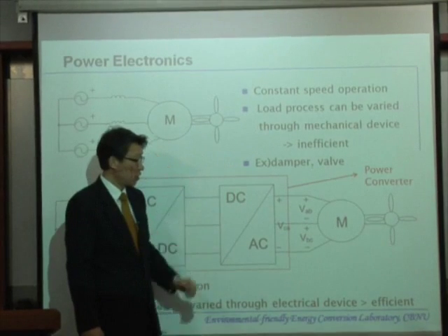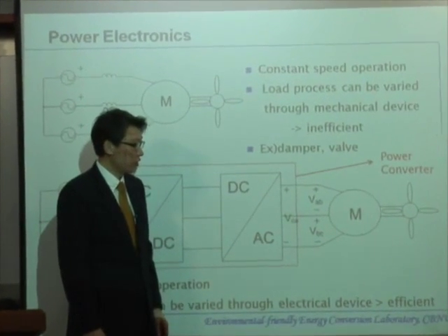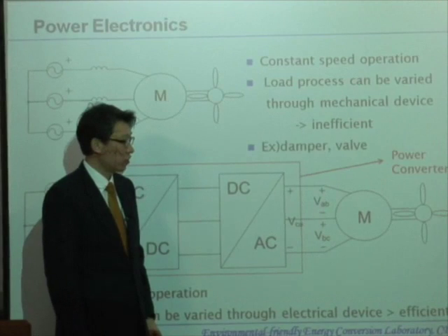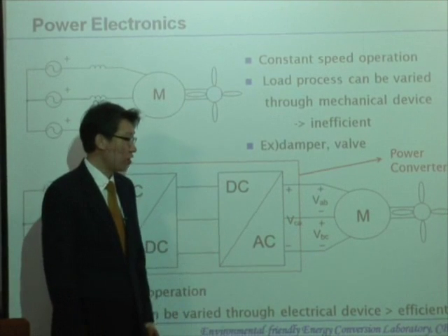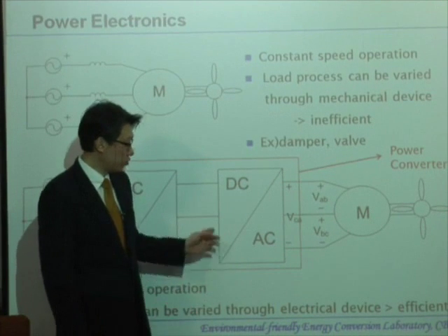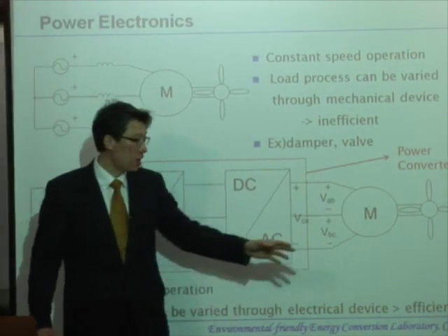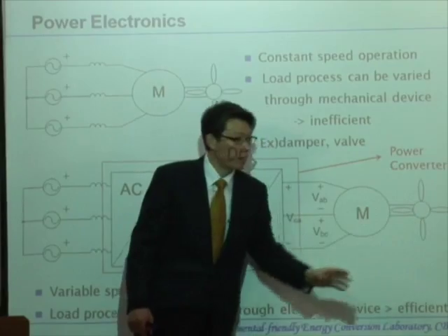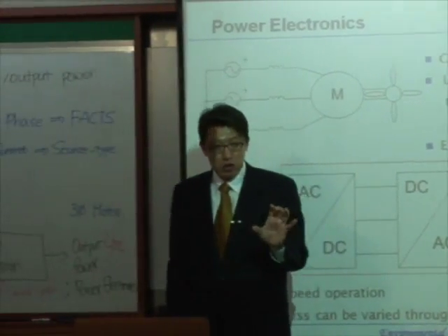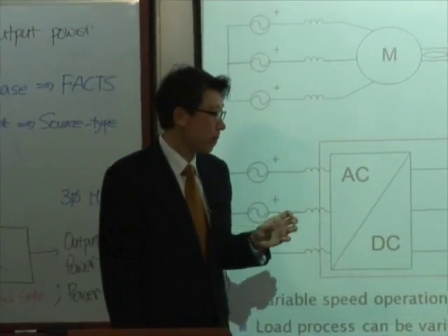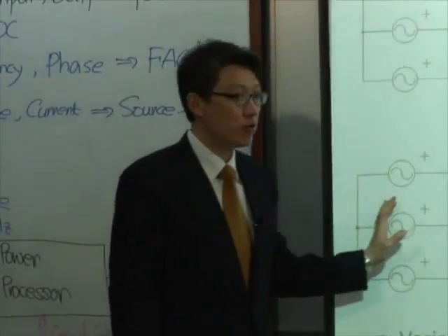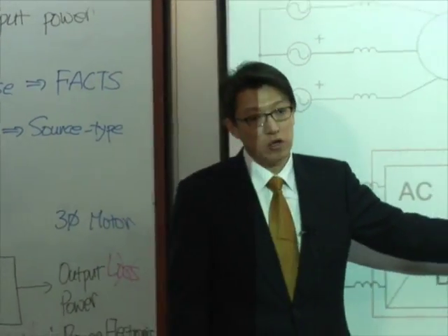So today it's like weather. When it's not so cold, we have to decrease the amount of airflow. Then we control this inverter to lower the frequency. And the fan speed will slowly go down. Okay? So it means the power flow is also controlled.